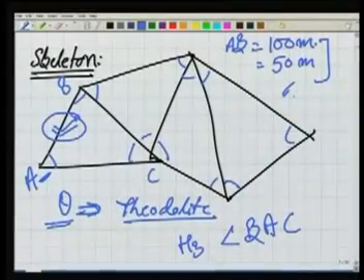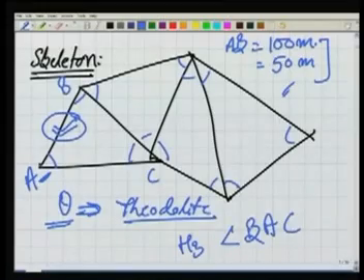So in that case, your length of the sides or the base length will be small. So your length could be only 100 meter or 50 meter or so. In that case, you can directly measure it using the tape or chain by spreading the chain or tape on a flat stretch of the ground and also applying the corrections.